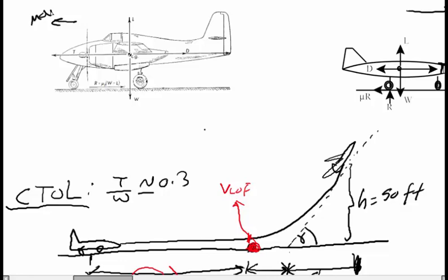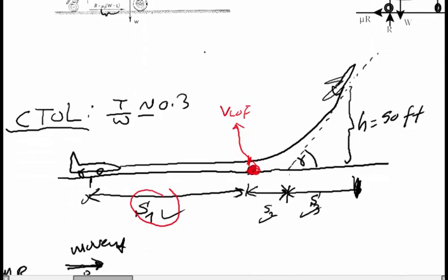When the aircraft is at rest, we have no lift, so it equals only the weight, so R will be very big. When the aircraft starts to generate more lift, this quantity is reduced and goes toward zero as the aircraft runs along the runway, until it will be zero when the aircraft is in the air.